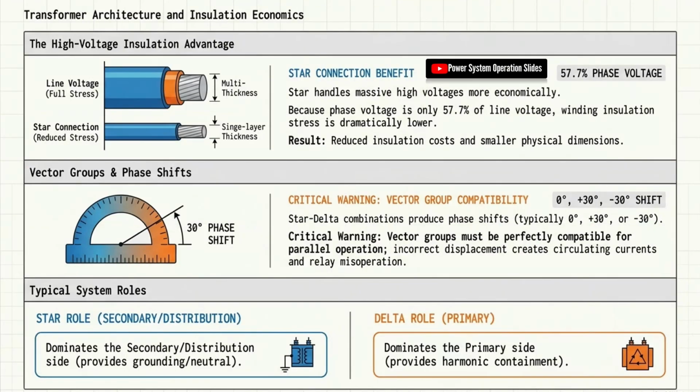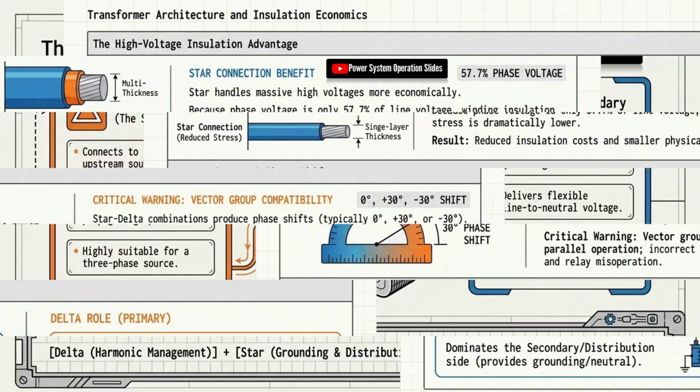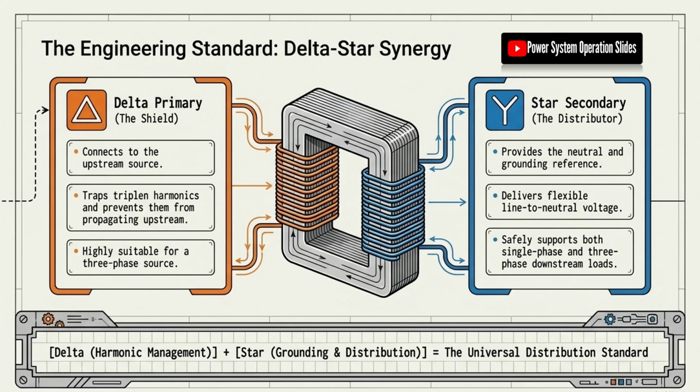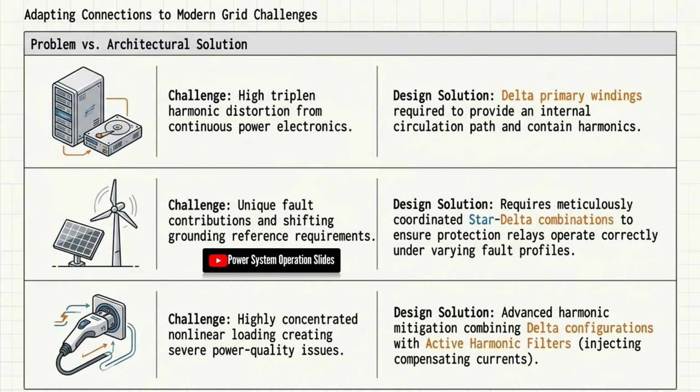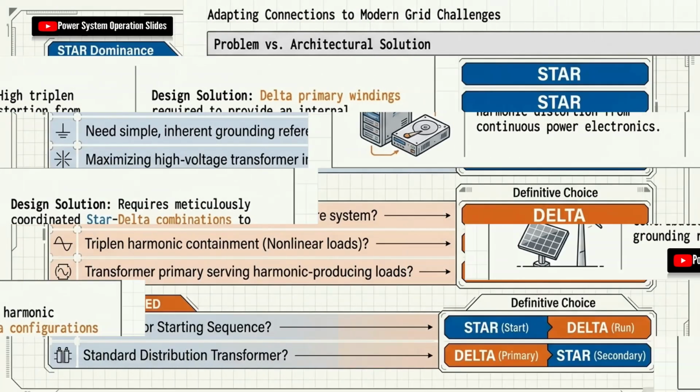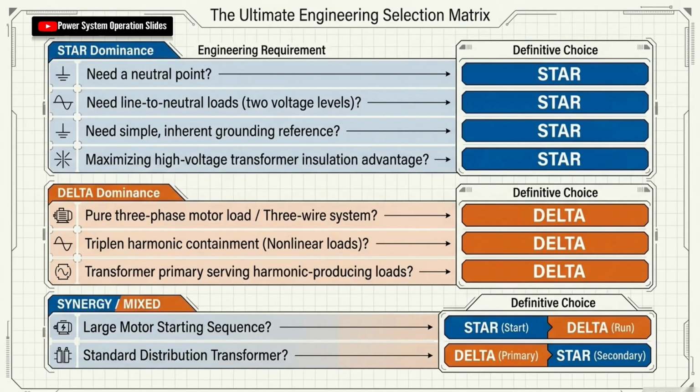From an operational and maintenance perspective, engineers and technicians must understand the connection arrangement, grounding method, phase relationships, transformer vector group, and protection philosophy associated with each electrical system. Ground fault protection settings can differ significantly depending on whether the system is solidly grounded star, resistance grounded star, or delta. Phase rotation and transformer phase displacement must also be verified before equipment is energized or transformers are operated in parallel. Maintenance activities must take into account the possible fault current paths, neutral arrangements, grounding connections, and transformer configuration.